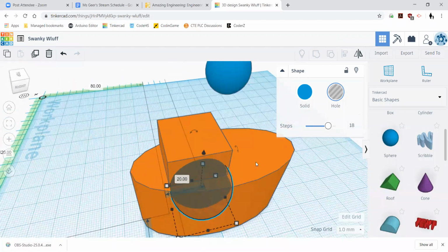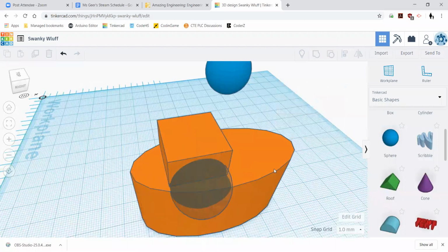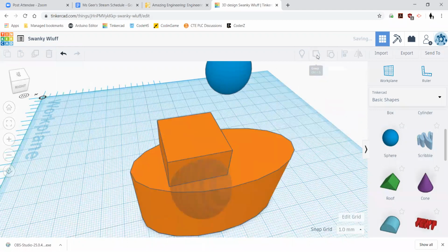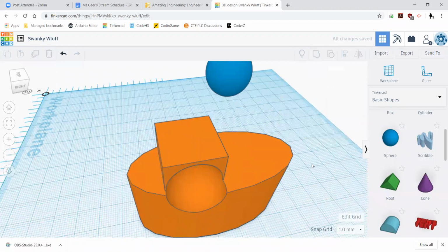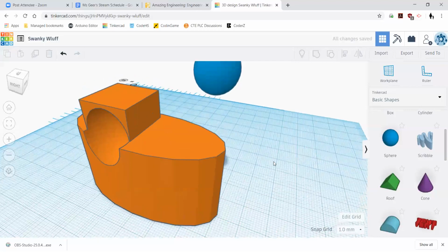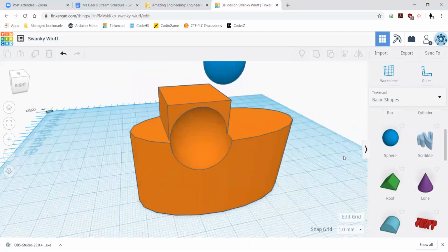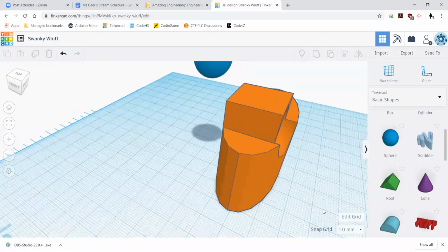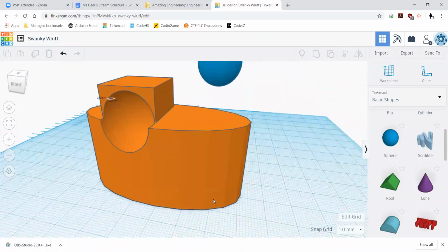You can see through it from the side and see kind of into that shape. So now when I choose both my solid grouped object and the hole, I'm going to hold down Shift and click that sphere hole. And now when I group these, it has cut that sphere shape out of the side of my larger shape. You see that okay?